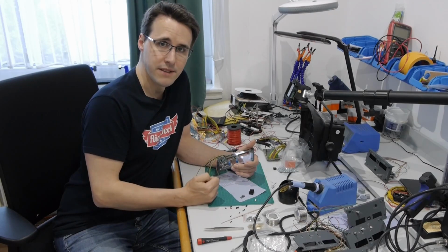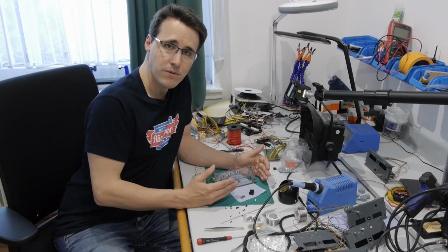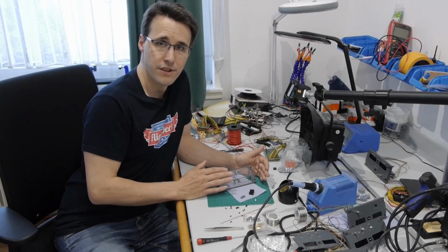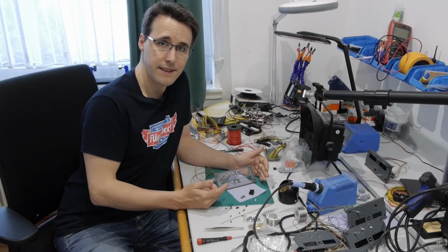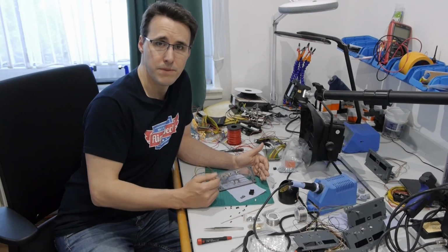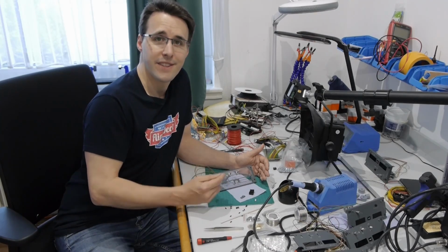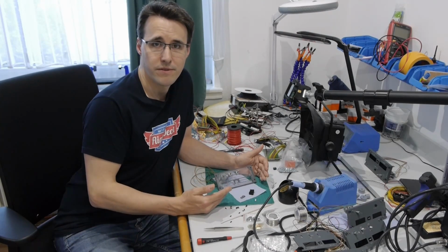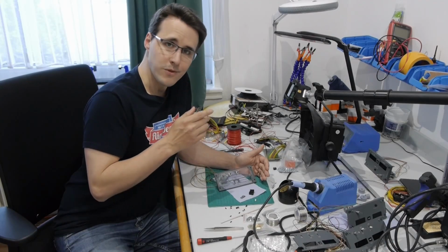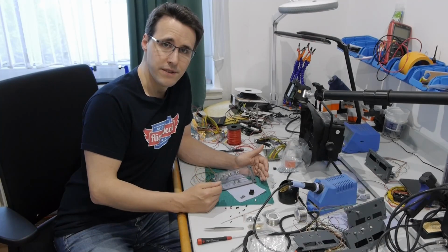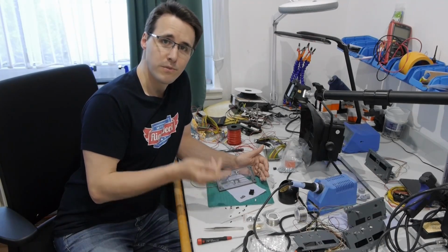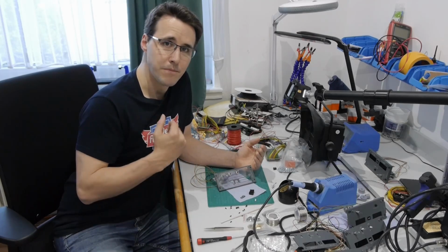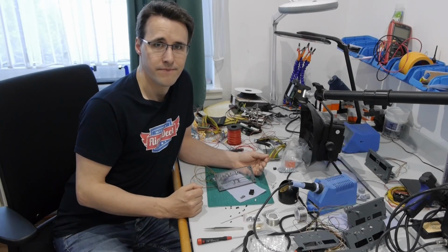There are 3 pins in the back. But if I would use it as an on-on switch, which is possible on the hardware side, because when you're looking at the back there are 3 pins visible, then this would cost me 4 extra pins on the Arduino. I only want to invest 1 pin per switch here, and we will come up with a solution on the configuration side later in MobiFlight to make this possible.